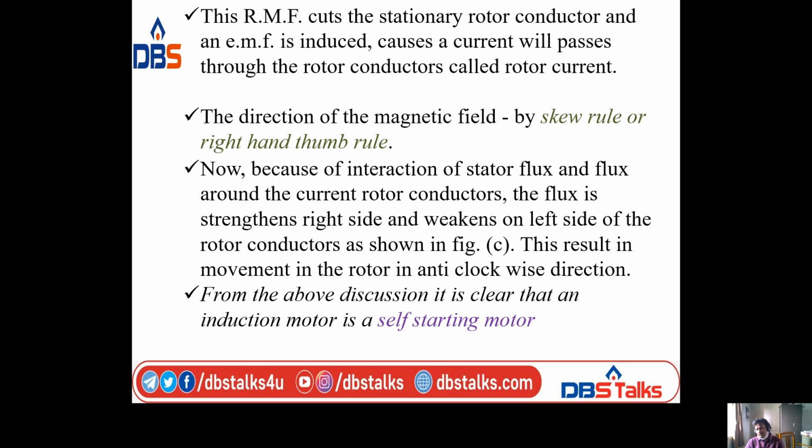That's why, even though the torque becomes 0, it will be re-energized. That's why the three-phase induction motor is a self-starting motor. Also, the three-phase induction motor is an asynchronous motor. Why? Because it runs lower than or higher than synchronous speed, but not at synchronous speed. That's why it is called an asynchronous motor, and it is a self-starting motor.